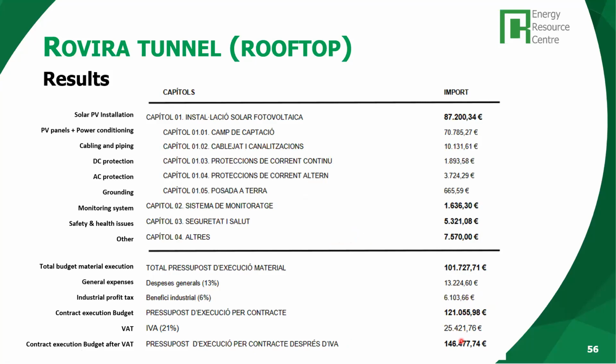But you can see, if we consider this investment cost, the turnkey cost, of 121,100 euros divided by 75 kilowatt peak, we have a reference investment cost of 1,600 euros per kilowatt peak, which is even less than half of the cost of the installation in the cemetery.